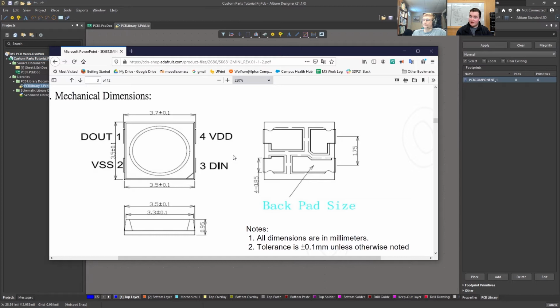And in this case, we don't. Also, read the application notes. Yes, often they'll say, hey, we were a little wrong in the data sheet, but in this application note, we'll say, you need extra vias or something like that. Exactly. But here, we don't have any of that.